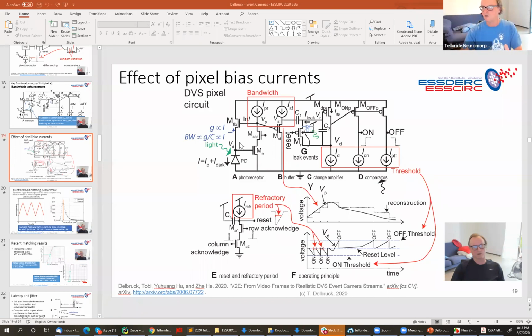Now, by many, many years of hard work, all those parameters have been hidden from the user, and the thing kind of adjusts itself so that it works. A perfect example is automatic exposure control, the thing that controls how long the frame is exposed for. It still doesn't work perfectly because it sometimes over and under exposes, but those algorithms which control the exposure duration are actually quite sophisticated. They're not trivial feedback control algorithms.